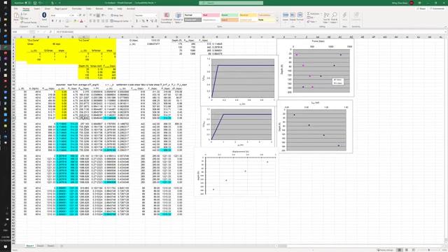So pretty much this is the elastic compression loading, and this is the mobilized side friction along the piles. And you know the depth of that segment, so that gives you a good demonstration of the axial load. So pretty much this is axial load. The blue is the axial load, and the pink is the mobilized side friction.